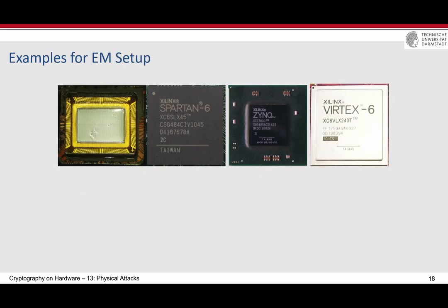Yeah. These are, for example, some FPGAs that you have used. I mean, you use Artix 7 in the entire lecture. Here you see Virtex 6. Zynq is also from the 7 series, then Spartan 6, and another FPGA that I don't remember. Here you see they are decapped, and there are the bonding wires, which means that the package is connected to the die. And here is the plastic package. Here is the flip chip. Flip chip means that the chip is flipped over onto the package. But here is not a flip chip. Here the silicon is there.